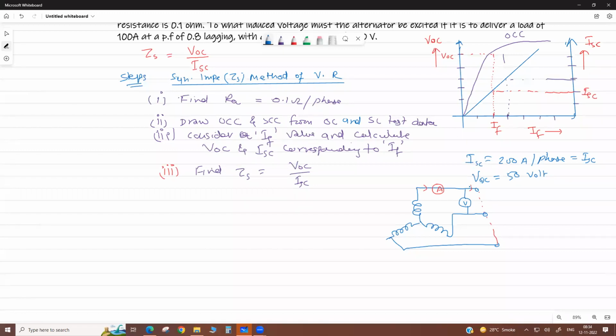Okay, and I always want to notice, please always sit with a notebook, pen and calculator, and I give a lot of time in parallel so you can note down the things, okay? So it is a line voltage actually. Now we calculate the per phase value, 500 by root 3. So this voltage needs to be divided by root 3. It comes to 288.7 volt per phase, okay?